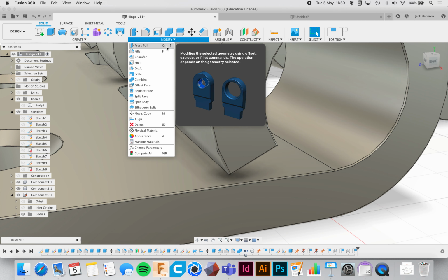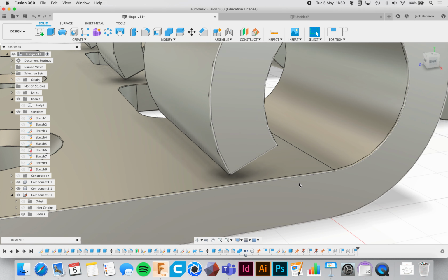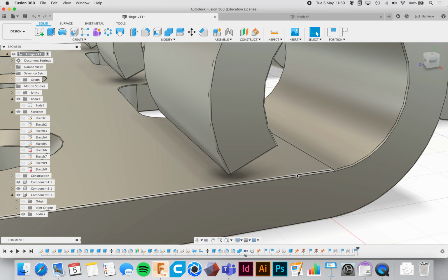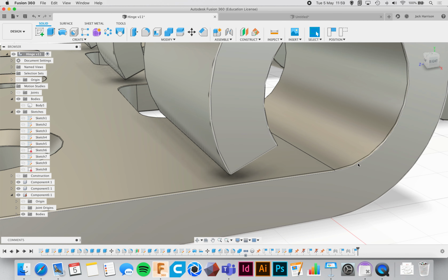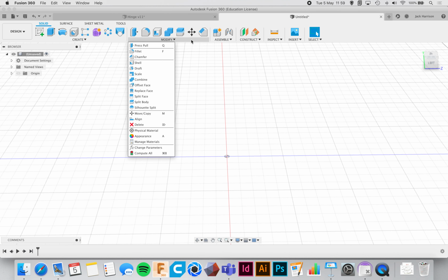These are the shortcuts. It's really helpful to use shortcuts. Now the reason you would add something like a fillet is because nothing in real life is completely sharp, so everything has a small fillet to it. Now these fillets in renders help to create a sense of realism because the light reflects off them differently. So you'd use this set of tools to create and modify those parts.